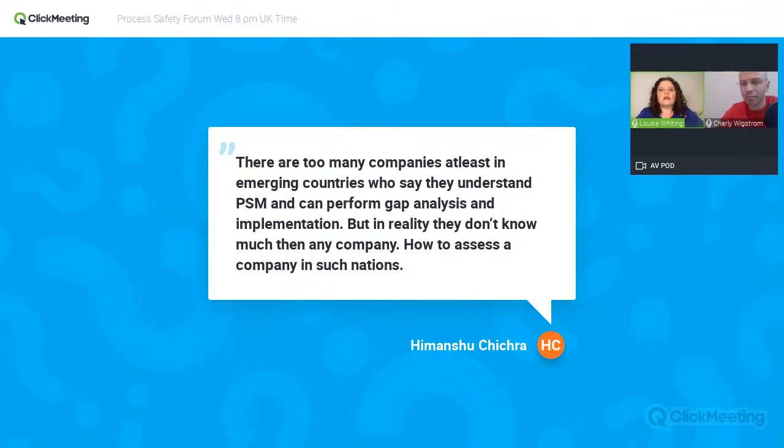You can say, okay, well, you're going to do me a HAZOP. Which international standard are you going to use? Exactly. And they go, there's not one issued. And you can go, well, no, actually there is one issued, and this is the one I want you to use. Then you can start to realize what their competence might be in HAZOP. If you're doing a quantitative risk assessment, you could ask them what their base data would be. And again, we could provide you some guidance about where you might get different base data. And if they use one of those, then you could think that they may know what they're talking about. If they go, oh, well, you just tell me, then maybe that's not such a good company to go for.